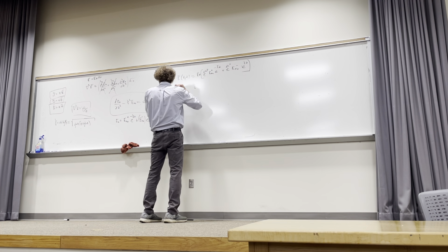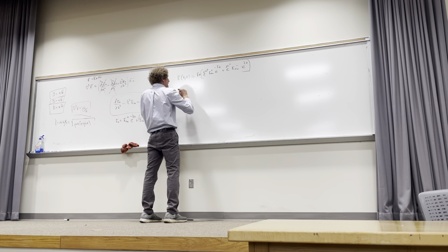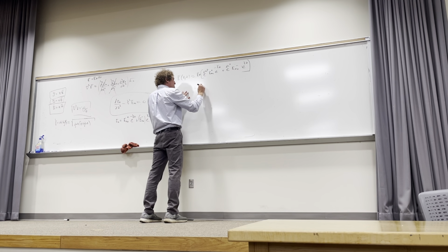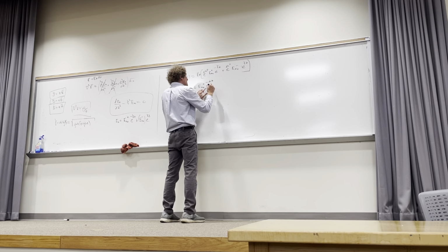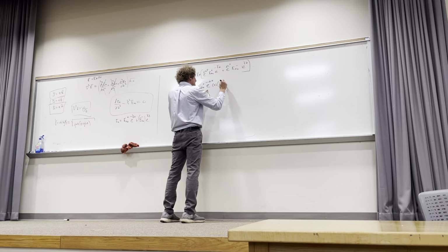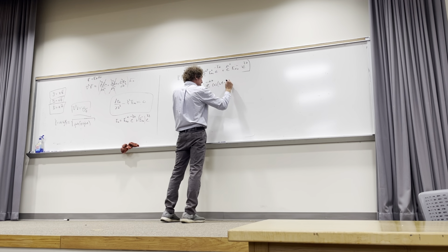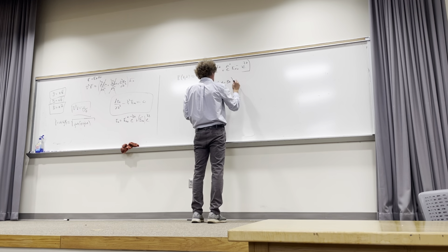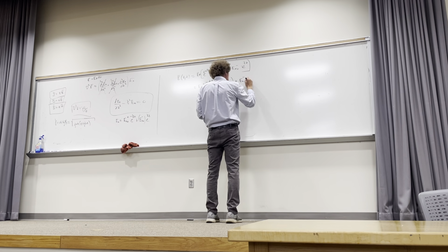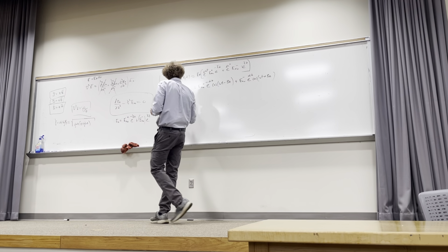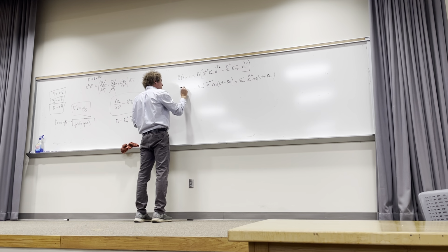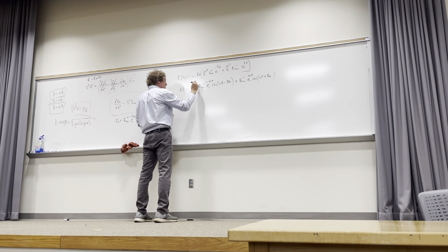When I replace gamma by alpha plus j beta, I would get Ex0 plus, then e to the minus alpha z, then the cosine of omega t minus beta z, and you would have plus Ex0 minus e to the alpha z times cosine of omega t plus beta z. And that would be the time domain solution. And it would be in the ax direction, of course.